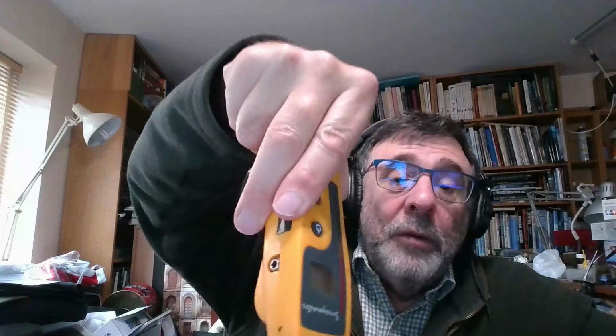Now, I have here, as I think I showed you earlier, a little bowl of salt. I'm going to shove this in. Bearing in mind, this is zero air, nothing. Put it in the salt, and I'm now getting a reading. I don't know if you can see it there, but it's about 14%. Okay, so that's 14%. Now, going back to my timber, at the moment it's reading 26%.